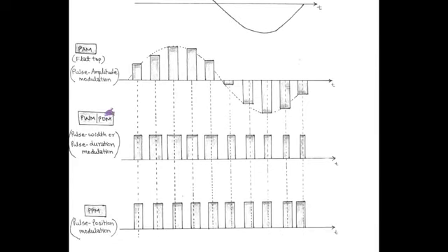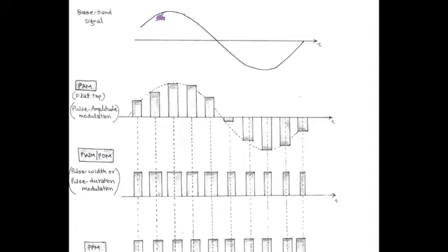Pulse width modulation is also called pulse duration modulation. So in PAM, that is called pulse amplitude modulation, the amplitude of the periodic pulse train with constant width, called carrier signal, is varied continuously in accordance with the message signal. Here practically we use the flat top sampling process with the help of a sample and hold circuit.